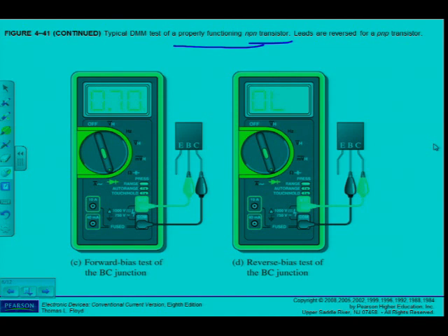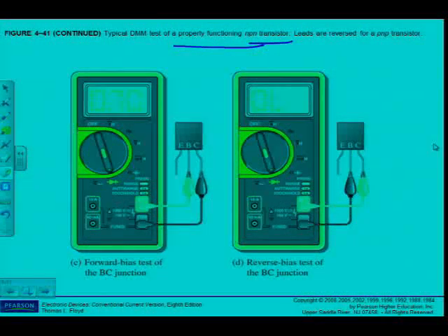What faults may occur with a transistor? Same as we had with the PN junction, the other device that we've discussed, the diode. The diode could either be open or shorted. Normally the most common fault is being open, but of course I'm testing a PN junction at a time here for a transistor. If the junction is open and I forward bias and reverse bias it, I would get the same value, which would be open line, or the value of the internal battery of my multimeter.